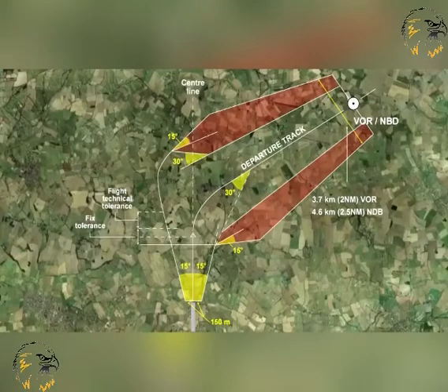If a departure requires a turn of more than 15 degrees, a turning area is constructed, and the turn required is to be commenced upon reaching a specified altitude or height at a fixed facility, like a VOR or NDB. Straight flight is assumed until reaching an altitude of at least 394 feet above the elevation of the DER. At least 90 meters of obstruction clearance must be guaranteed in the turning area. You should note, especially for examination purposes, that 30 meters is approximately 100 feet. This fact will allow you to make sense of many of these difficult heights.